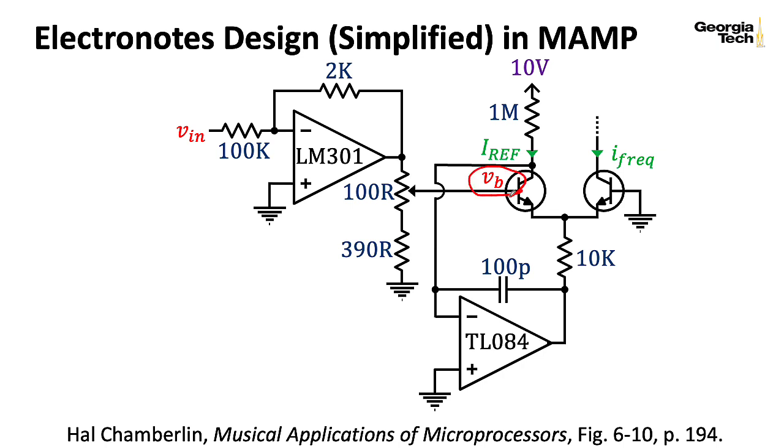So over here, this VN, that would usually correspond to a volts per octave kind of source that's coming from an old school Moog 1960s controller keyboard where it's basically this big resistor chain. Or maybe it's coming out of a modern MIDI to CV converter that uses that 1 volt per octave standard or whatever your standard is.